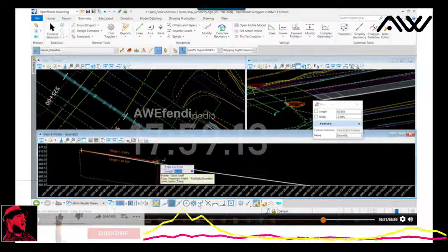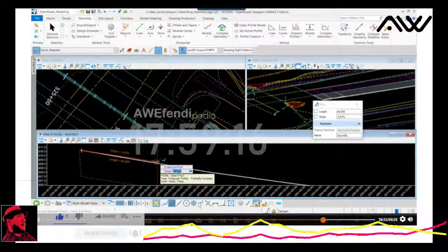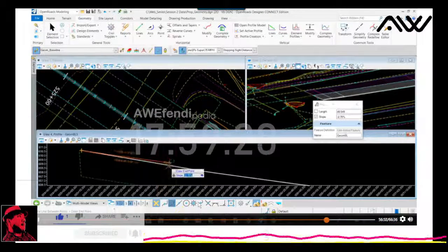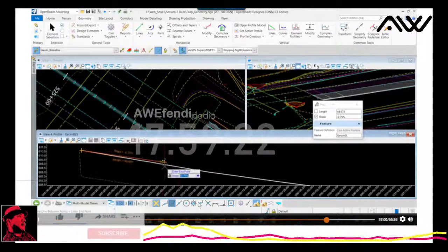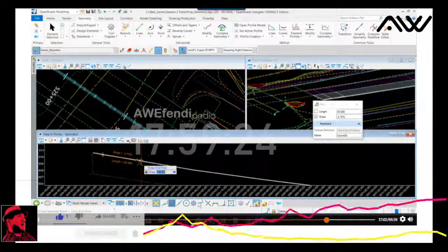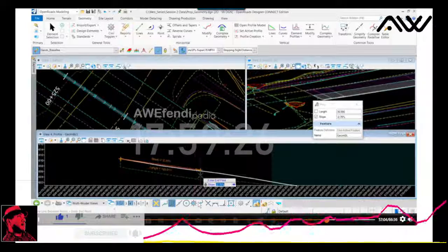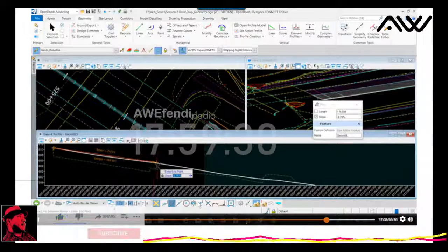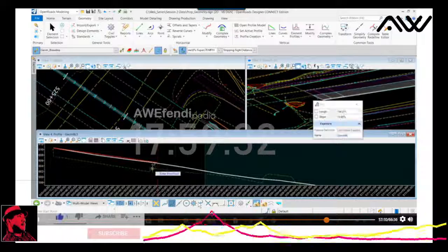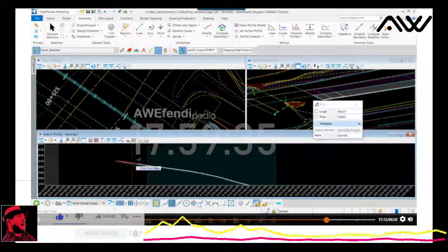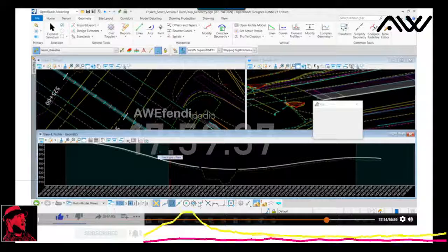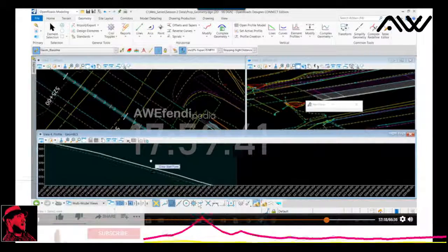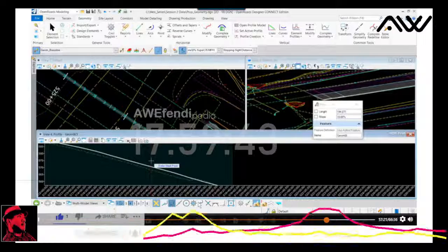So this first element, we can draw this out. I'm going to hold to a 2.75 grade. So I'll key that value in, and you can see that value. I can actually zoom out. You can see that it fits a little better than maybe it appears. And then draw that segment in. So I have a tangential segment along that edge of pavement. It uses, again, that proposed widened edge of pavement using the existing cross slope of the road.